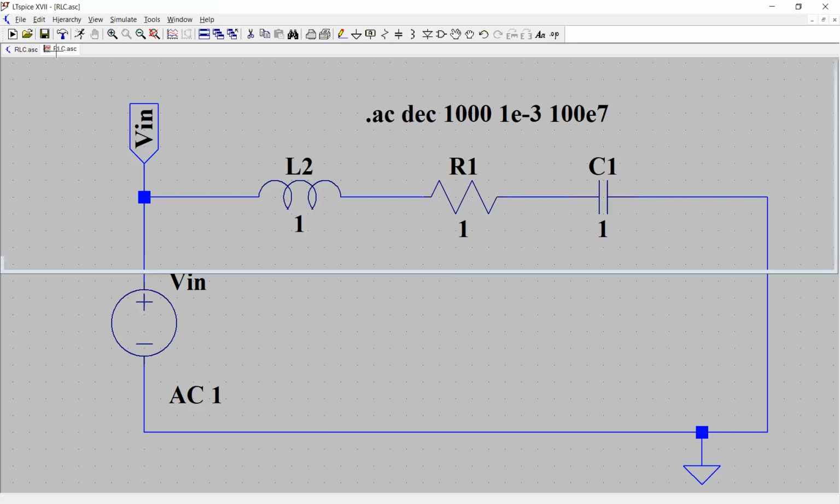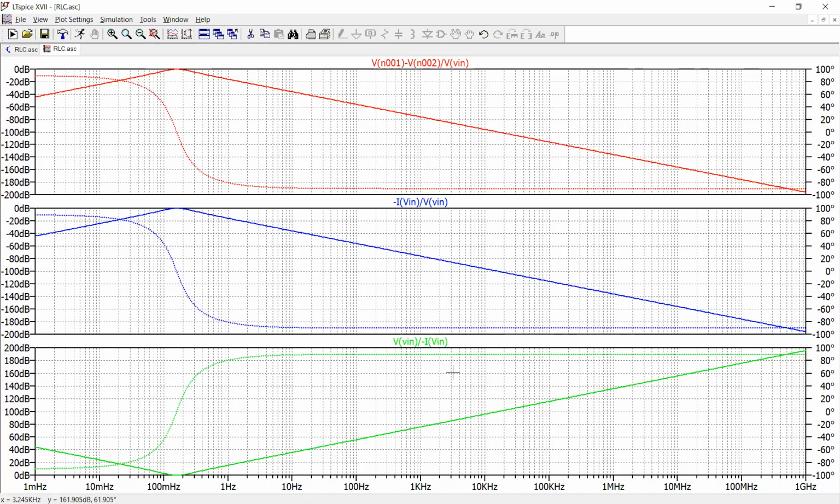Okay, so look at this graph in the bottom here. What we have plotted is the voltage divided by the negative of the current. This is just for the fact that we explained here, the direction of the current is negative, just to match with the theoretical results, because SPICE does the opposite. In SPICE, the direction of current is opposite to what we conventionally took.